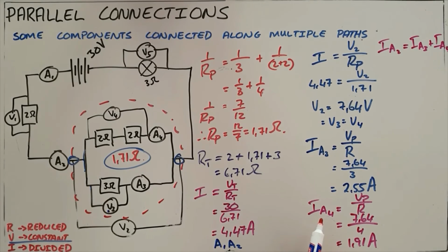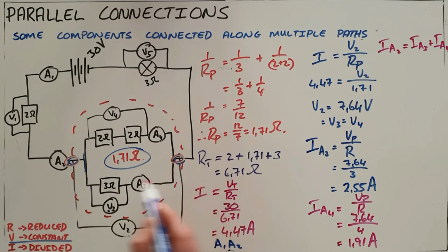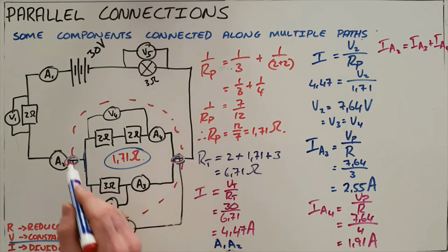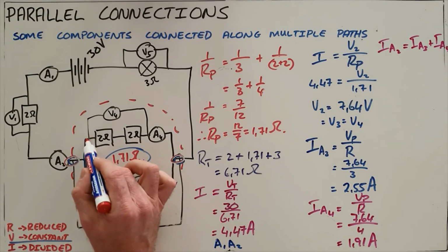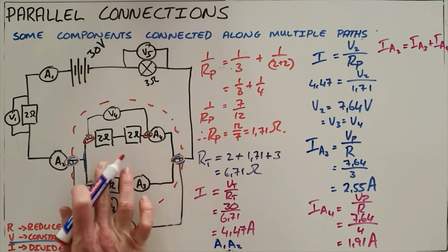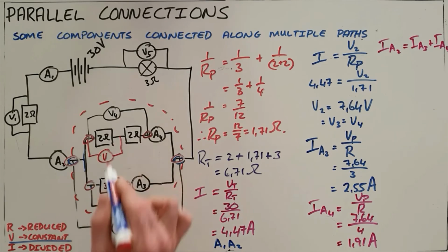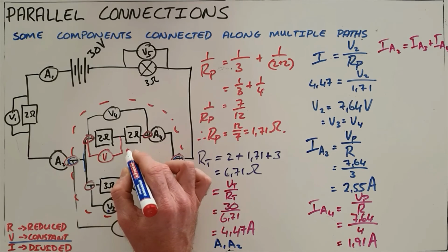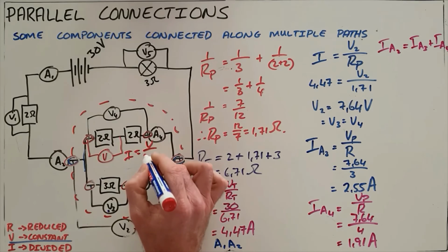So as we can see here, the rules, once you understand them, allow you to use Ohm's law to solve for unknowns. It is very important to understand that the voltage measured across the entire parallel circuit is equal to the voltage measured across each arm of the parallel circuit, provided that it covers every resistor in that parallel circuit. If we wanted to calculate the voltage over only one of those resistors, that would be a separate value, because the voltage here is different, as it is now being divided in that series circuit.